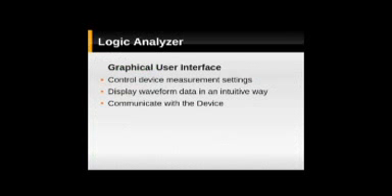flip-flop. The logic analyzer GUI provides the same function as the oscilloscope GUI. The user controls which logic level the device responds to, how many samples are to be taken, and at what rate the samples are taken. A trigger can be set to respond to an edge to control when the data sampling starts. Data is received and commands are sent through the same USB port as the OSCOPE GUI.